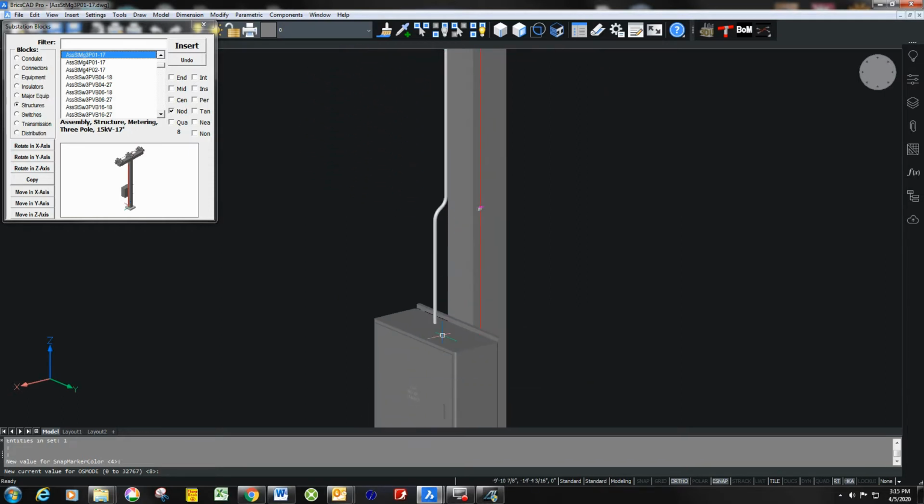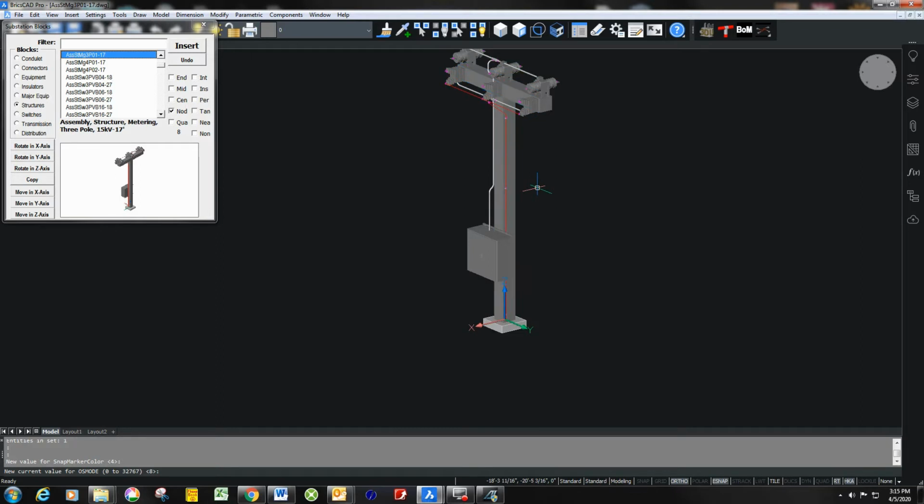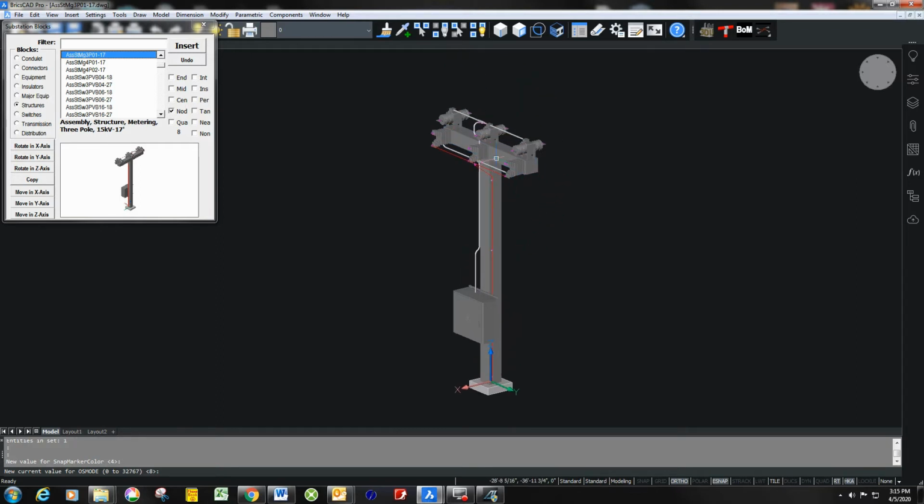It comes down to a meter cabinet, which is a block. All this conduit is conduit. Got some more conductor. This is some number 4 grounding conductor for those VTs. So this is a block that has nested within it other blocks, and that's important to understand. So this is a block, and these are nested one block deep.